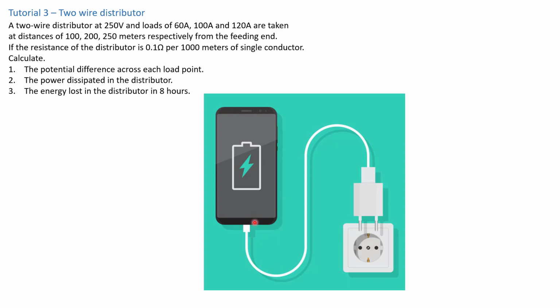Because considering the fact that most smartphones today charge at about 2 amps of current, right? So if you have 2 amps of current going through this cable, and this cable has a high resistance, that means it's not a very good cable. That means 2 amps with a high enough resistance, there's going to be a significant voltage drop.